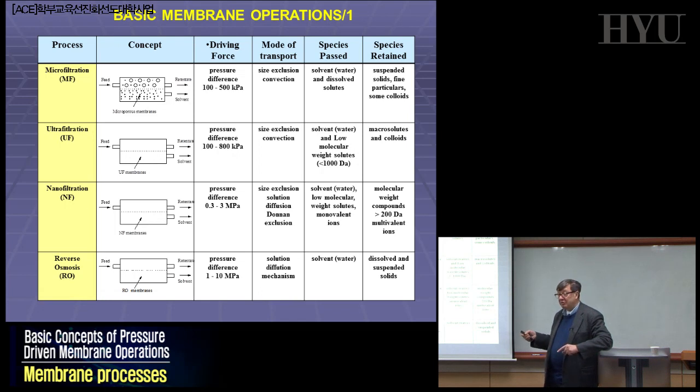Microfiltration is a system in which you can remove some of the particles, some of the components at the origin of denaturation and the change of the properties of your milk, and not the others. So most of the milk goes across your membranes with no thermal treatment, so you don't destroy anything, and the species at the origin of the problem just stay in the retentate. And that is what we call cold microfiltration.